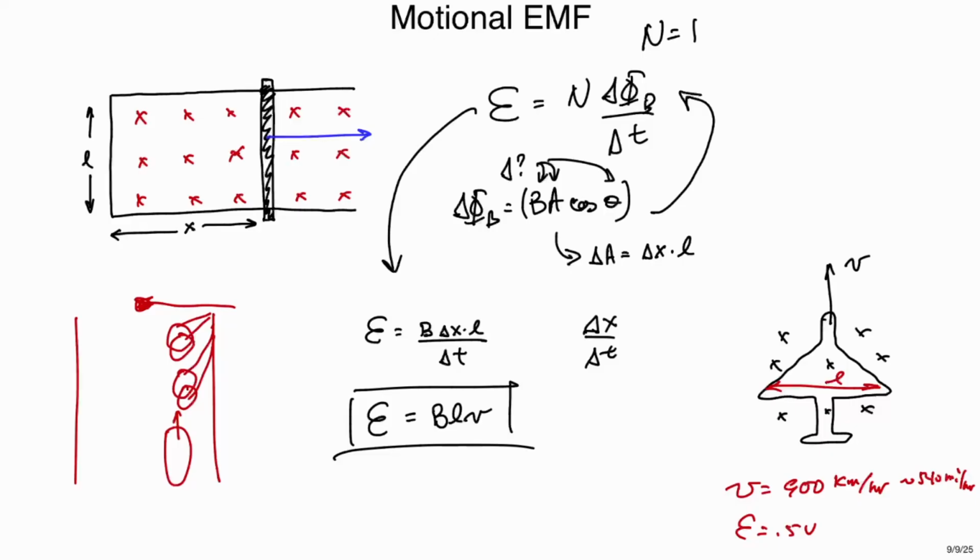It's supposed to be able to tell whether or not traffic is there or waiting at the light, okay? There are other sensors, but that is a main one. You'll see them on the highways too. That's how Google Maps knows what the traffic is, among other things. They can get data from the Caltrans network about how many cars are going over per time, and how fast the cars are moving over the sensors. Google then aggregates that with other people that have turned on the ability to share information about where they are at all times. And you get this picture of traffic patterns and all kinds of stuff that's going on. So all of that is being brought to you by Faraday's law of electromagnetic induction.